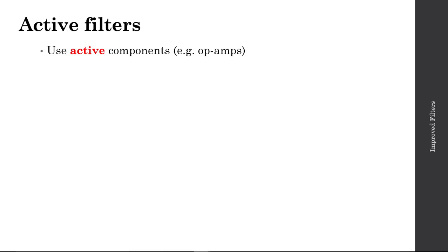One in particular is if you're trying to build a higher order passive filter, you're going to need to implement inductors in your circuit. Now, inductors tend to be very expensive and they're often difficult to implement in an integrated circuit. So often we prefer to use op-amps then, right? So they're advantageous as compared to the use of inductors for these higher order filters.